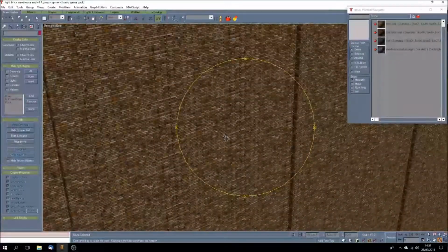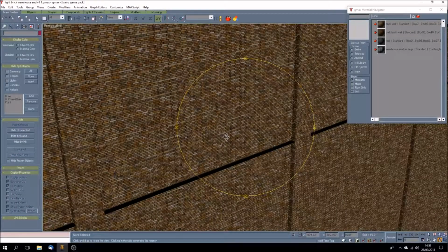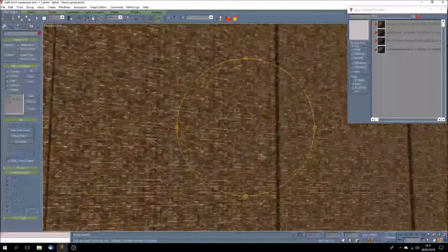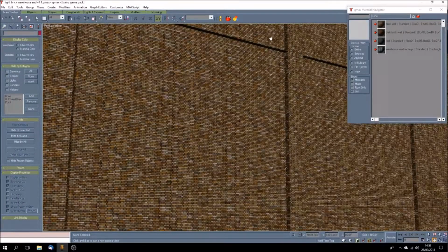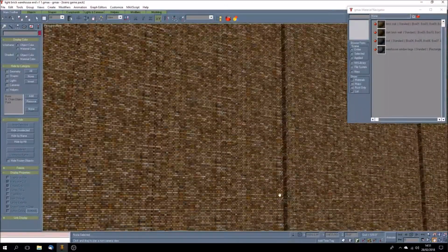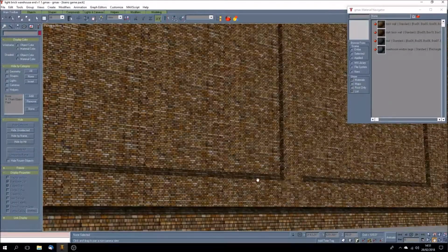You can see there actually that I've got different faces even in here. There's a cross piece there, look, which would show up. That was the dark brick and would show up here. So I've actually got quite a shallow mesh going across there and more deeper meshes going up the top. And when you come down to the base of the building, we'll keep going, it's a tall one. Then I've angled these and carefully made sure that the textures that I've textured it 3 bricks wide at an angle, and also try to make this texture the same number of bricks per length as this.